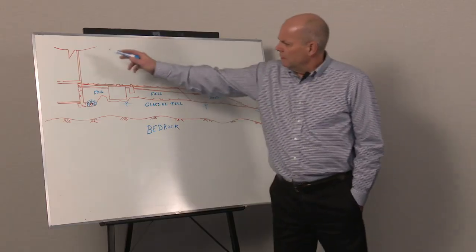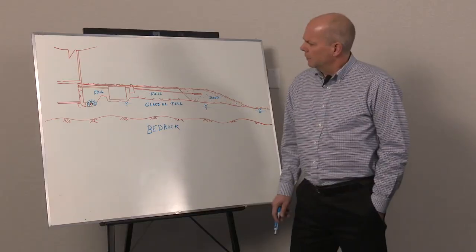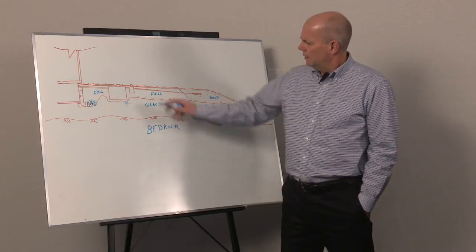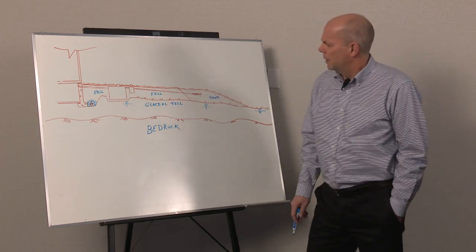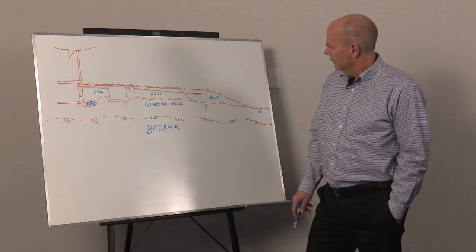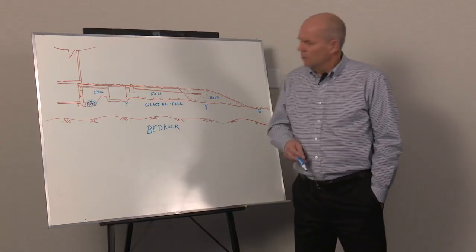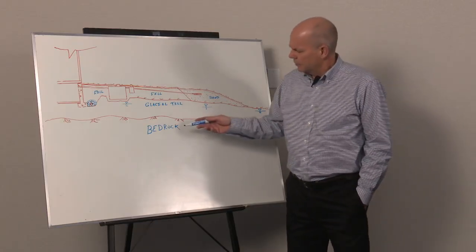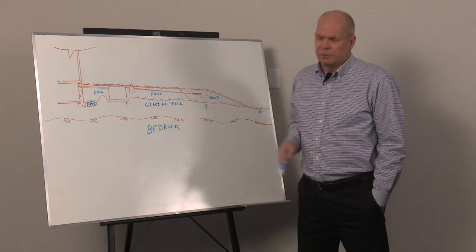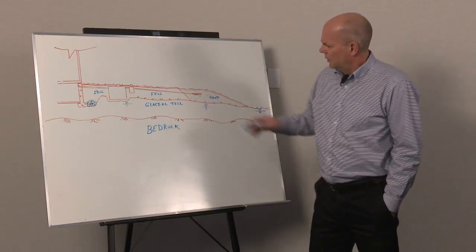So we start at the dwelling, and we have an effluent pipe that leaves the dwelling and feeds a septic tank. You may have a siphon box, pump chamber, an effluent pipe feeding the field, the sand bed of some sort. Typical site conditions throughout Nova Scotia would consist of bedrock, which is usually below any type of construction you're dealing with. If bedrock was at the surface, you would have other problems.